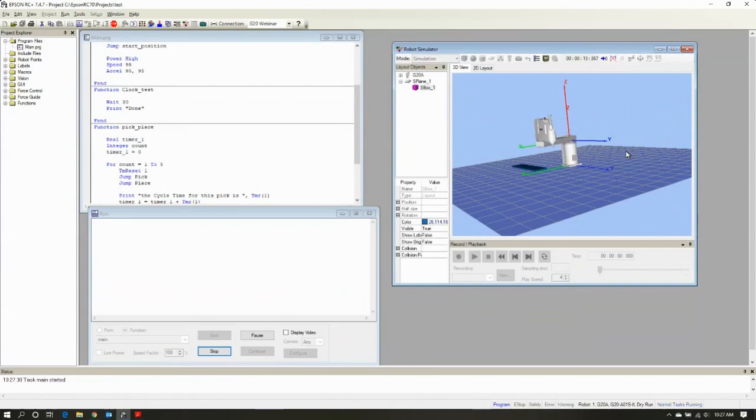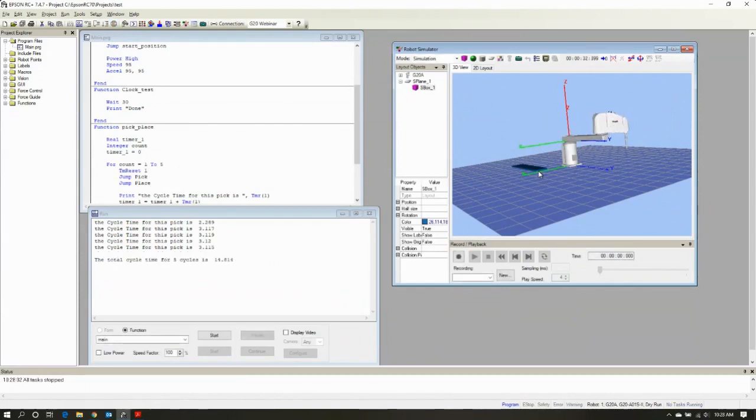We don't begin moving in our horizontal fashion until our quill goes all the way up. Most of the time, in fact, the vast majority of the time, we can begin moving horizontally while we're still moving vertically once we clear our obstacle. So we can allow this to be a little more efficient. We don't have to wait as long to travel.